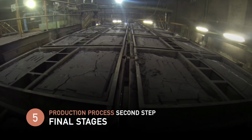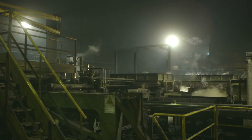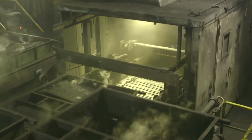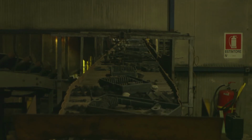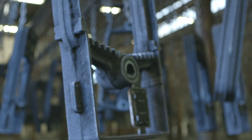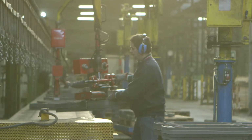After casting, the cast iron products are left to cool on the floor for 50 minutes, then taken out of the flasks and placed on vibrating platforms to clean off the sand produced by the core breaking up inside. Next, the 700-meter-long air cooling carousel and shock blast unit for the final cleaning of the manufactured pieces.